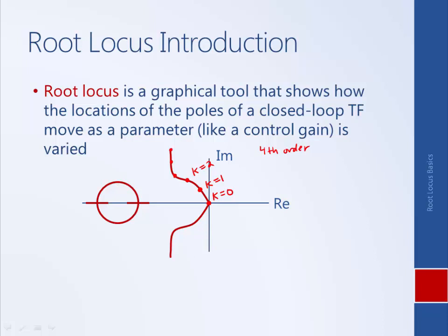And by knowing where the poles are, we can figure out which poles are dominant. We can figure out, are they indicating that the response is getting faster? So moving the poles to the left in the complex plane corresponds to making sigma larger, which corresponds to a faster settling time. We can see what the effect is on beta or zeta to get a sense of overshoot, things like that.